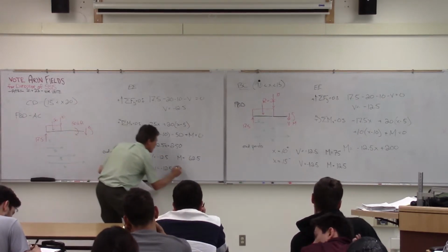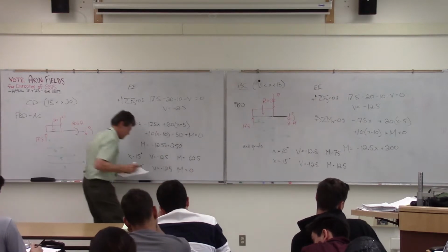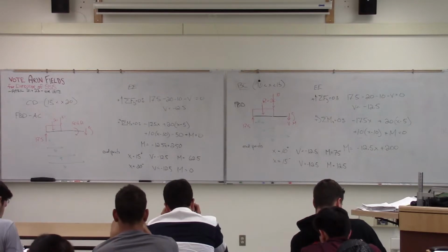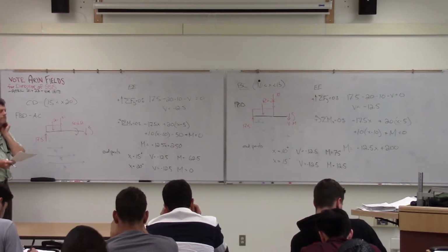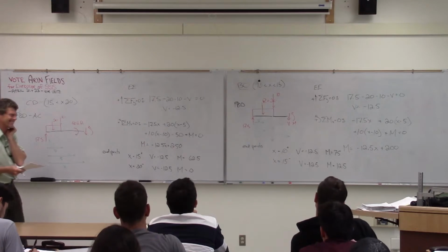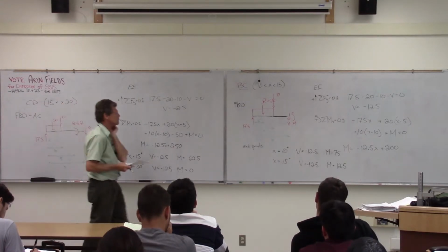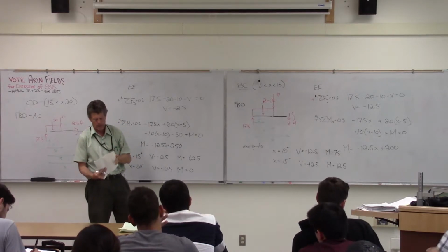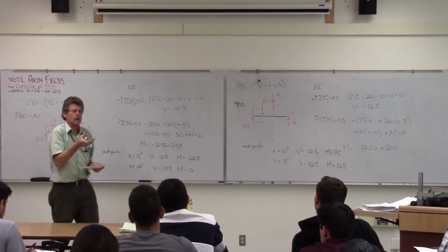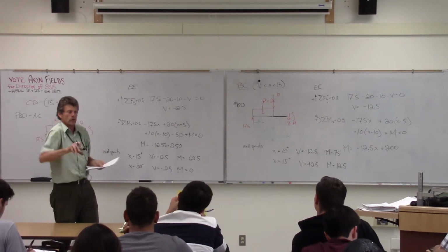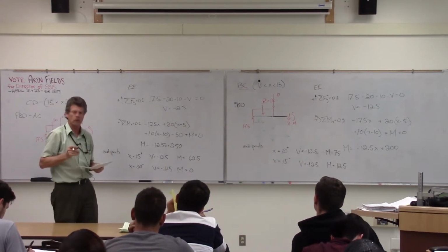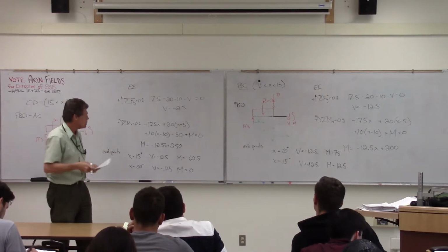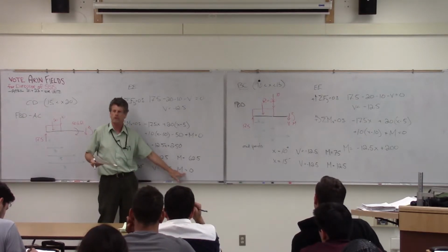When I plug in the new values for m, however, it's equal to 0. Does that make sense? Yep. Why? There shouldn't be any moment on either side. You're right. There is a, what is it, a roller on that side or a pin? Okay. But there's nothing there to support any sort of concentrated twist, right? It's free to rotate. When we see that thing bending because of all those loads there, it's not going to resist rotation at all. It's going to allow it to rotate, which says then that I have no moment capacity there. I should have no moment.